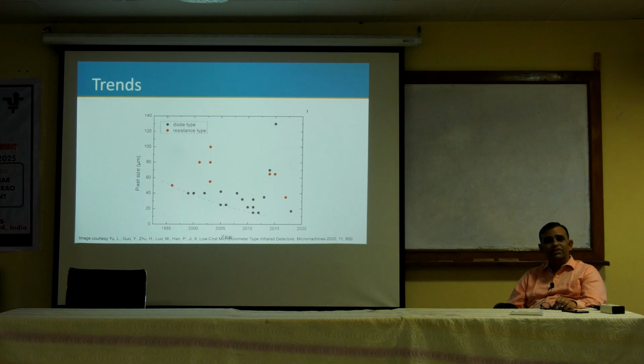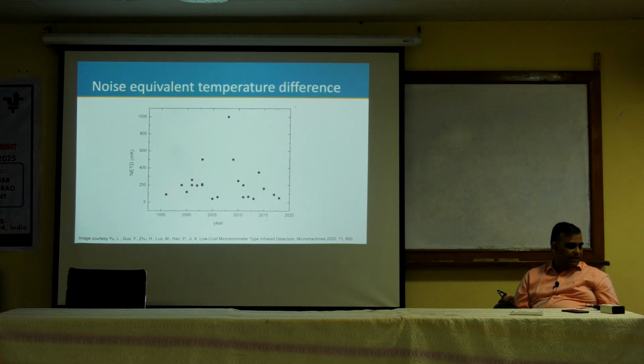But the other thing worth checking is, what was the size of the diode sensor which we took in while designing the camera pixel? 3 micrometer by 3 micrometer. These are still significantly bigger than our camera pixel. We are looking at 20 micron, 60 micron, or that kind of sizes. So while we can make an array, the individual pixel is still comparatively larger, which means the number of pixels which we will have is still fairly small.